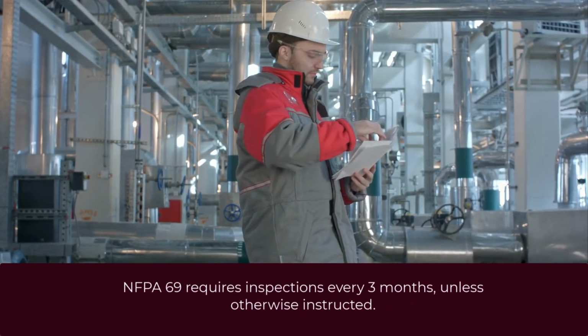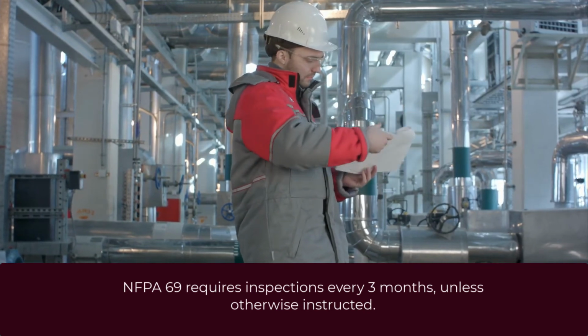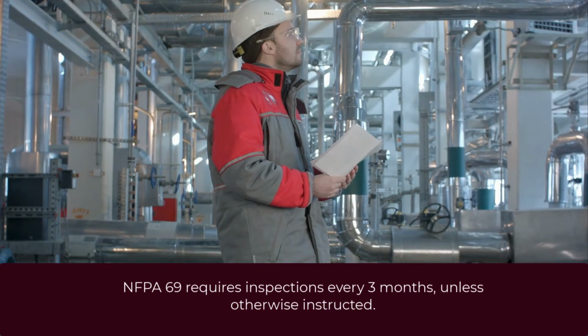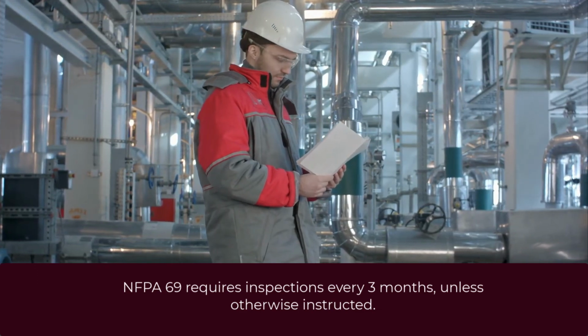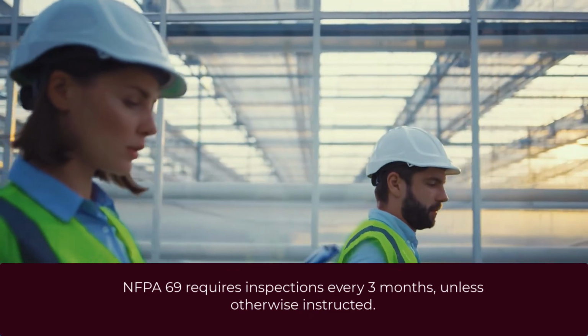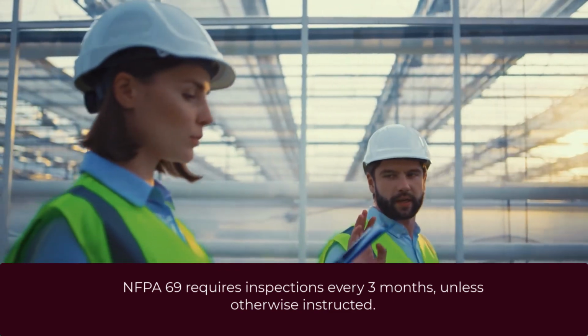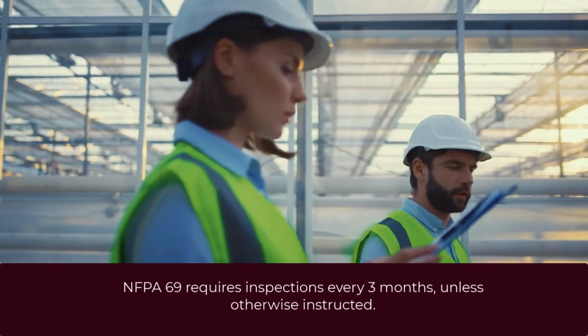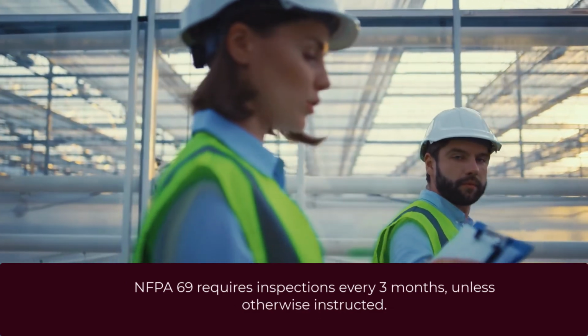Every explosion isolation method, whether active or passive, needs routine maintenance. NFPA 69 requires inspection at 3-month intervals. This frequency can be modified based on documented operating experience and hazard analysis, if approved by the local authority having jurisdiction and the designer. Inspection records must be kept on file for a minimum of 3 years.